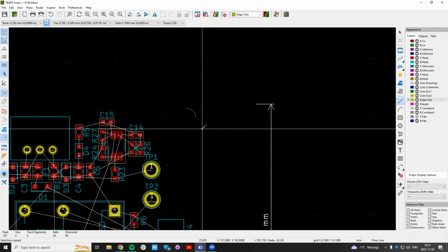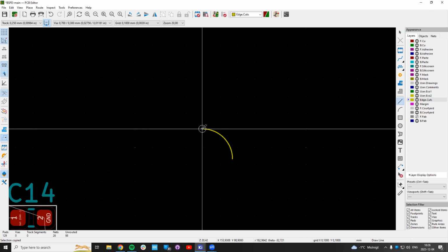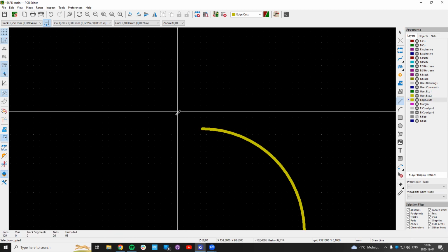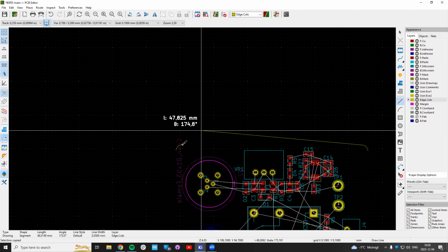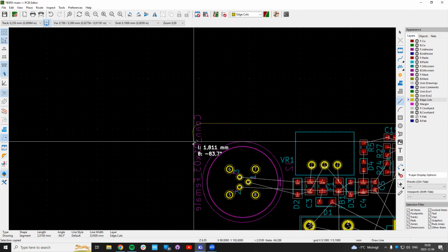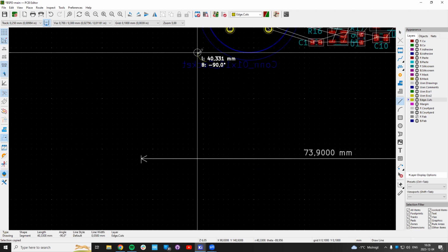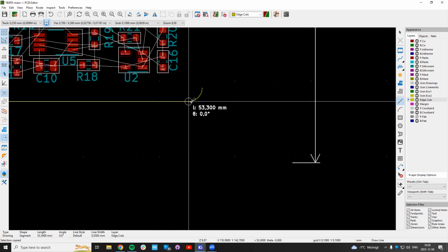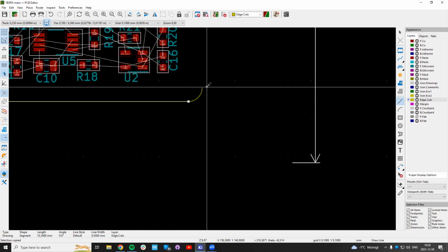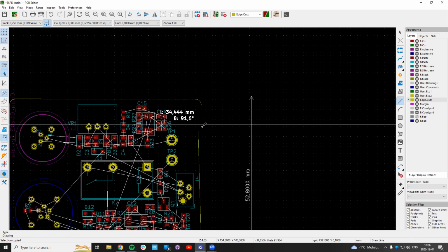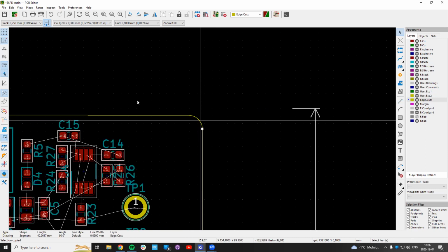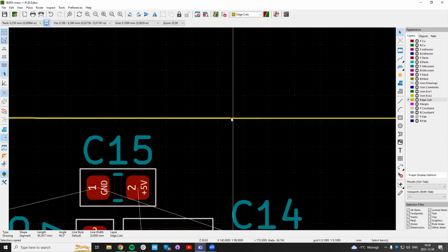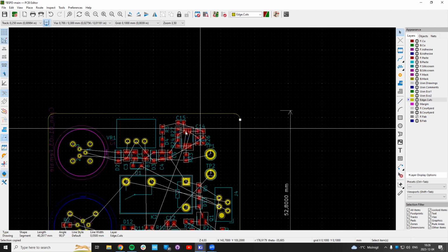Take the straight line tool. And now it's important that you don't just click here, it will complain. You have to wait until you get this small white circle. Okay, like so. Now we go here. If you really want to, you can spend a lot of time making this angle 0. If one of my angles aren't 0, no, they're all good. 90 or 0 degree angles, which is good. This line is not perfectly straight, but it's so little that it won't matter.